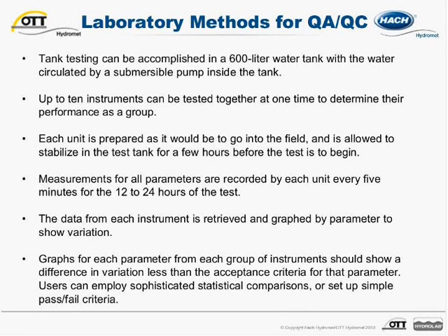It's important to prepare each instrument before testing using the same methods that would be used to prepare the instrument for field use. Instruments need ample time to equilibrate with the environment before testing begins. Record measurements for all the parameters every 5 minutes for 12 to 24 hours. Afterward, graph the data by parameter, so one parameter per graph, and review the data for analysis.